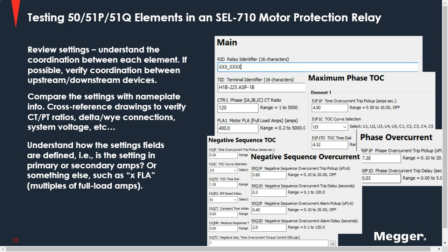It's important to be able to understand why, because you're out in the field and usually on a time crunch. It's important to thoroughly get into those settings and really understand what you're testing. If at all possible, set up your tests beforehand. Look at the setting and know what to expect.